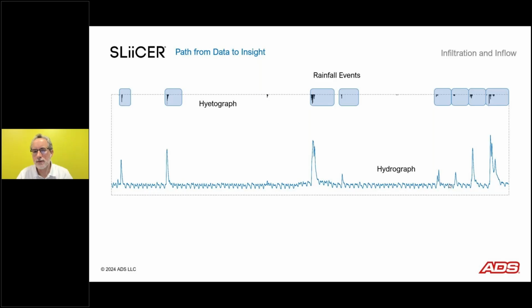The first thing we need to do is get a handle on rainfall events that have occurred, and not just every rainfall event, but the ones that are most significant to us. If you look in most data systems or most data exports of rainfall data, you'll find that it's very easy to roll up the statistics on that rainfall by daily totals.